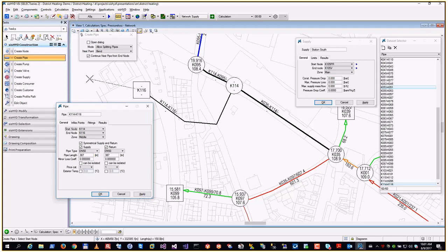In MicroStation, you can use the right mouse button to reset an operation. So with a right click, I can do 2 times. I can stop the pipe construction, or you can just click the pipe creation command again.